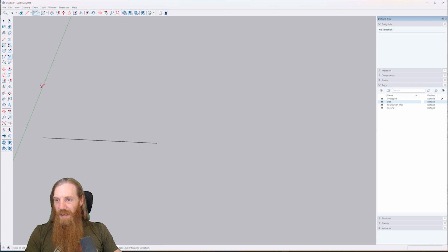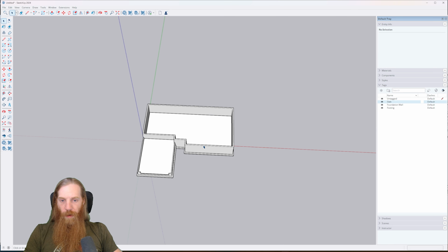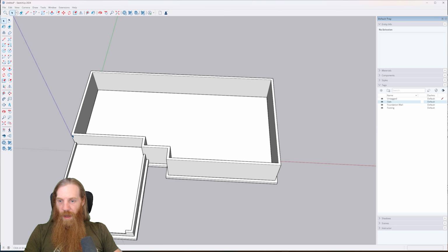I don't model it because it takes a lot of time, and there's not really a point to, because in order to get a measurement for all my rebar for the build, when I'm trying to do my material count, I can just use my tape measure, measure this wall, measure all these walls, get lengths of everything, and then add up my total length and multiply it by the number of runs of rebar that I need, which is typically 1 run every 16 inches vertically in the wall, and then your footing is usually going to have 3 runs spaced horizontally apart.